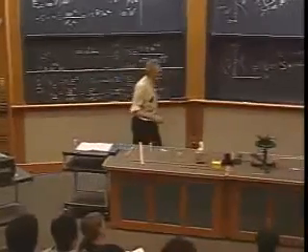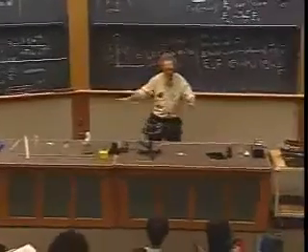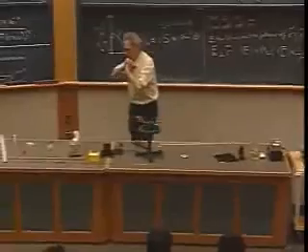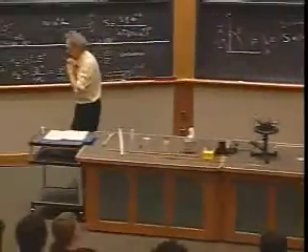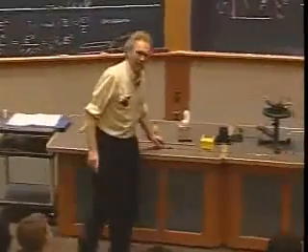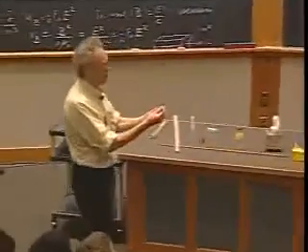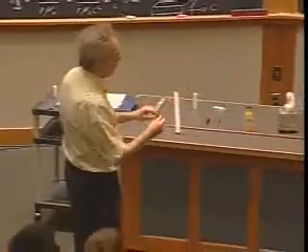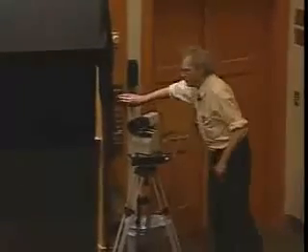We have here an 80 megahertz transmitter. We've seen that before, wavelength 3.75 meters. I demonstrated this before to show you that the radiation is linearly polarized. I demonstrated it by having this receiving antenna and rotating it like this when the light went off and rotating it like this when the light goes on. Today, that's not my objective. Today I'm interested in the sine squared theta term, for which I need a little bit of assistance from someone.